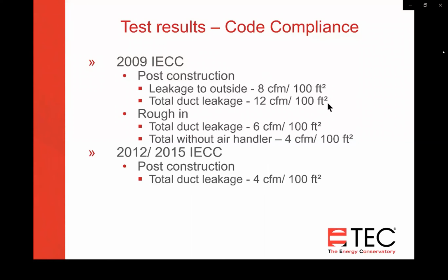So it's counting the duct leaks inside and outside, and it needed to be 4 CFM per 100 square feet of floor area. We ended up doing a lot of training with contractors to show them how to do the duct leakage test, how to find the leaks, and also how to seal. We did hands-on on how to seal the ducts and then test them after you sealed them. And it's hard to get down to 4 CFM per 100 square feet of floor area if you're not used to building tight duct systems.